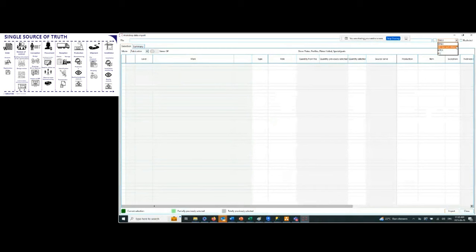For example, this is a workflow specifically for Tekla Structures. If you have the NC1 files and you export a specific bill of material, we can then keep the association between main part and attached part components, even though we're just importing the individual NC files. Because we have this additional bill of material, we can keep the association and how they're being grouped together by means of welding or bolting, etc.